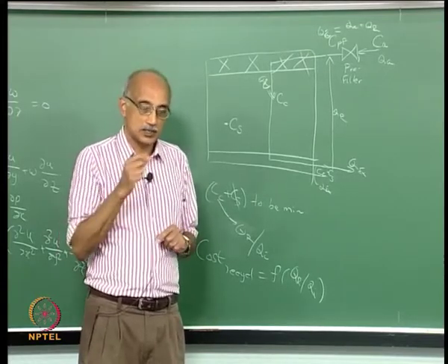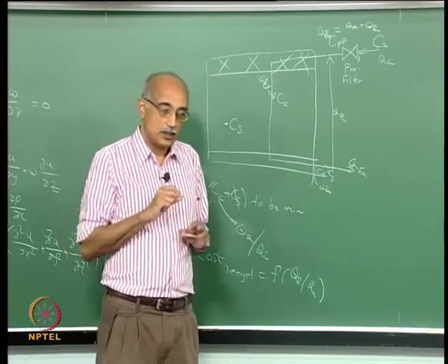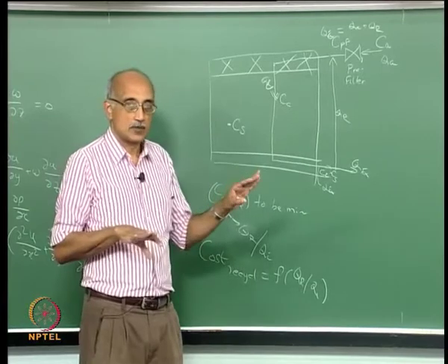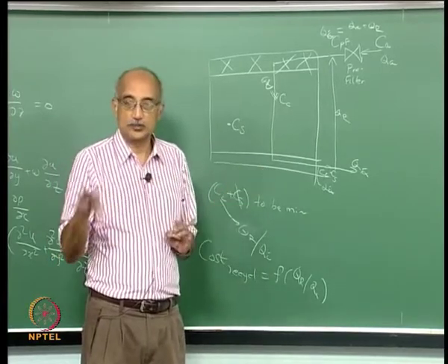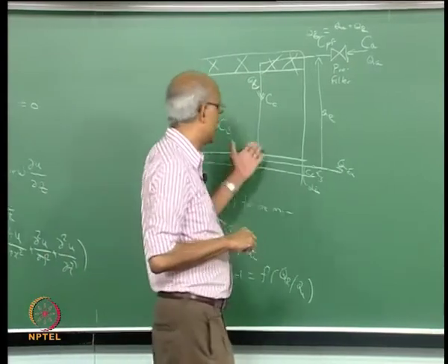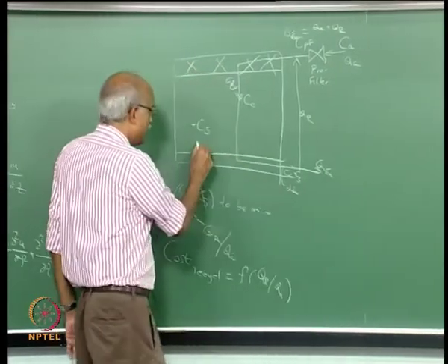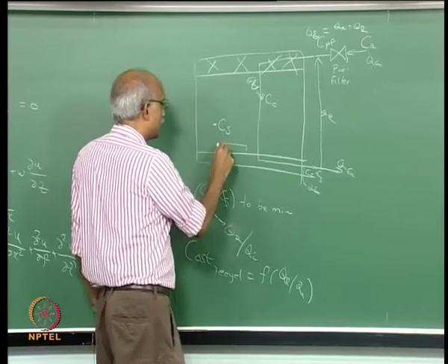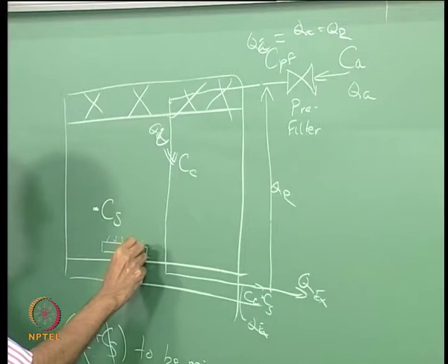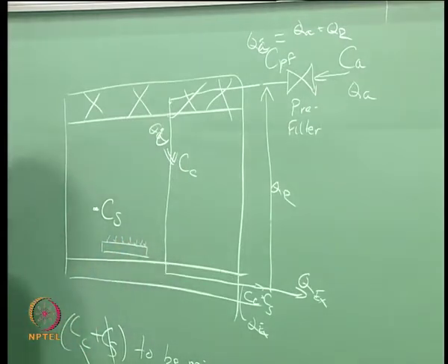Now as we have discussed in earlier lectures, the rate of deposition of particles on surfaces is a distinct parameter from the velocity with which particles are transported inside the clean room. So if you look at, for example, this clean room, what you really care about is, suppose you have a silicon wafer sitting here, how many particles are going to deposit per unit area for some period of time.